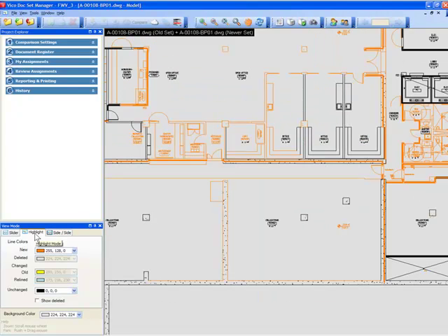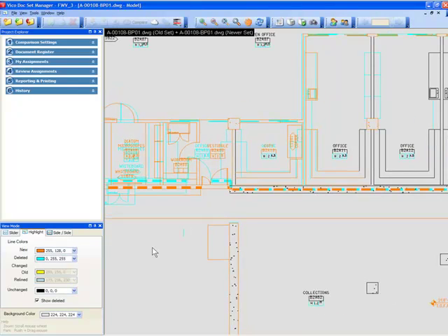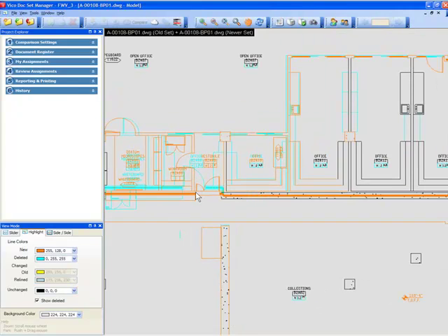Basically, highlight view mode is essentially the right side of the side by side, but bigger. And this is also a good place to maybe turn on what's been deleted. When I hit this button that says Show Deleted, my deleted color drop down becomes active, and then I can see, in a kind of 3D look with the orange and blue, what's been deleted. Okay? So we can see what's been selected and deleted and then added new in the new CAD file. So the tools are there for you to pick it apart any which way you want.